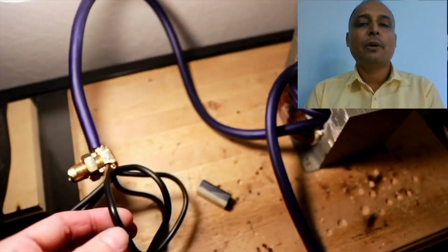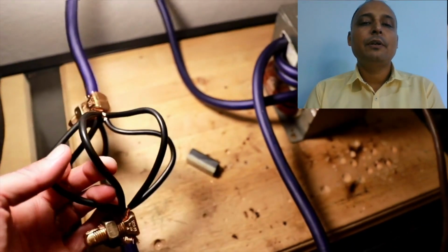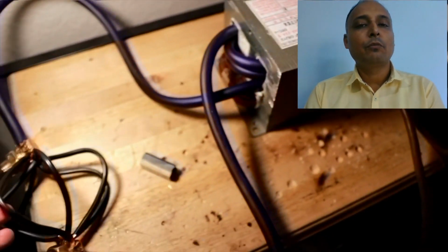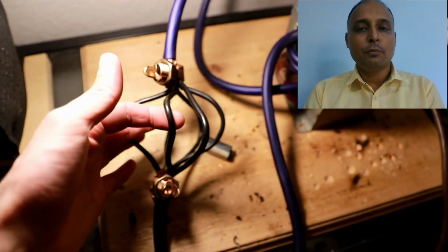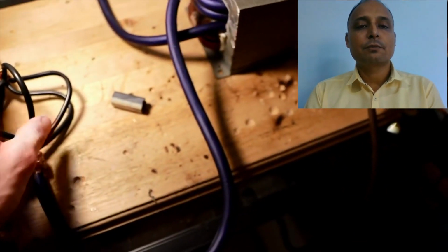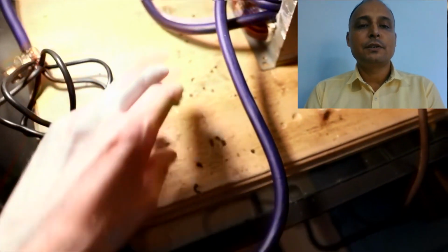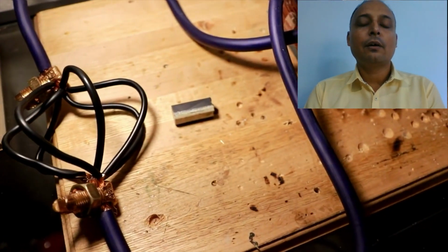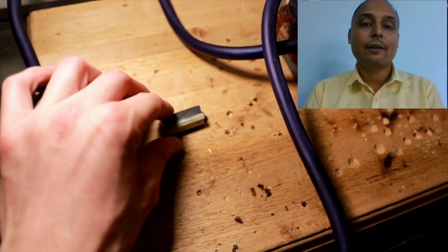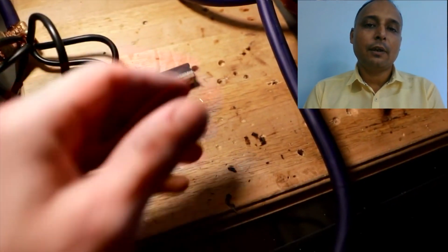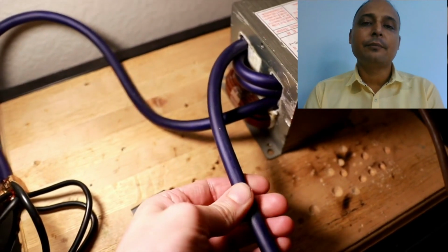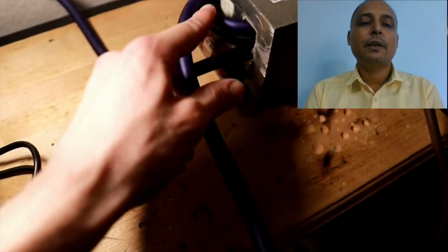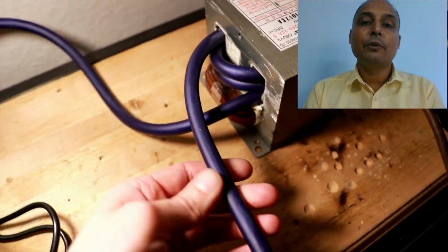Now we are connecting the power supply, and then when we switch on the power supply, we can see the movement of the magnet. And that movement of the magnet proves that the transformer winding is now working fine, and the secondary side is actually letting some high current flow through it, as we can see from here. So this way a transformer can be taken out and can be rewound.